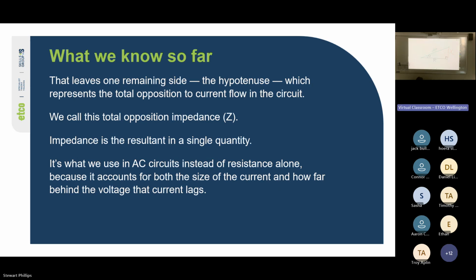There is the total opposition. We're making sure that the protection can trip in time. We're making sure there's enough current flow that if there was a dead short at that power point or whatever point we're testing, it's going to trip the circuit protection protecting that circuit. So we can check when we do the test versus Table 8.1 in AS/NZS 3000. They give values in that for us to reference so we can say whether it is a pass or a fail.